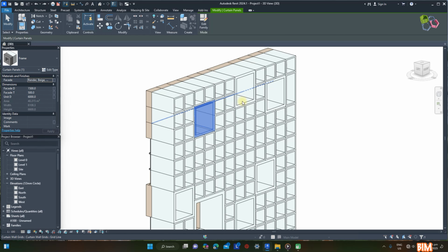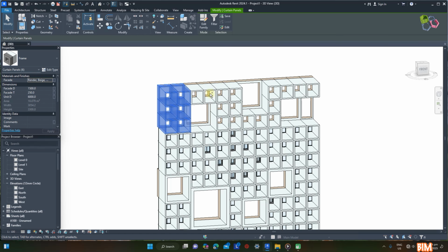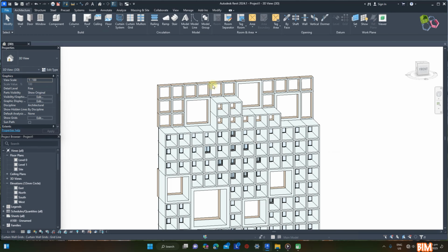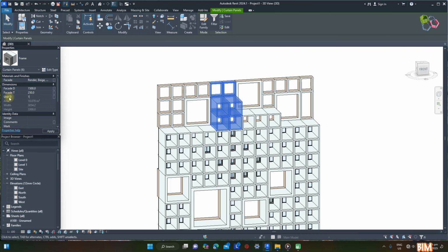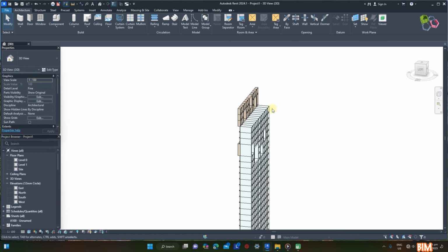According to the images, both the upper and lowest 3 rows are not required to build the units. I select the huge frame panels on the rooftop level. Modify the unit depth amount to 0, though it might break the parameter. To be clever, input should be 1 mm for ignorable thickness instead of a null value of 0. Apply to the remaining frame components at the top 3 rows. Input 1 mm. Also do all panels at the bottom 3 rows. All good.